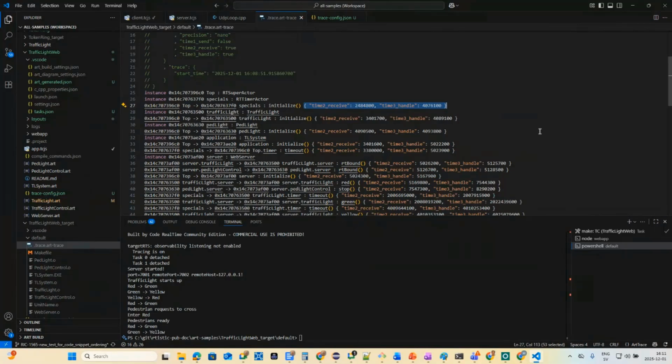You mean the opposite? If you have it in code real-time, navigation works, but if you have the model in model real-time, you cannot navigate from this trace file. Yes, I mean, if you generate a trace in model real-time and then open it in code real-time, the navigation to the model will not be working. But all other visualization and analysis will be available.